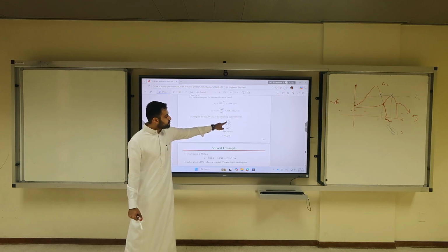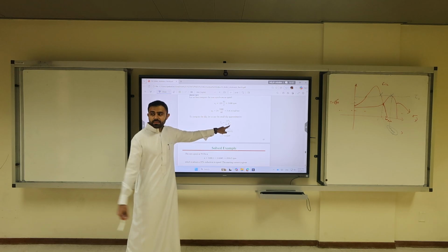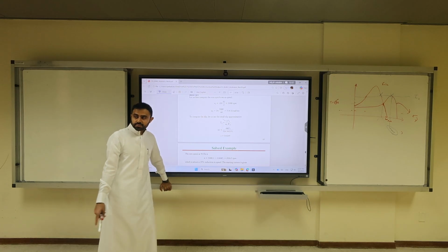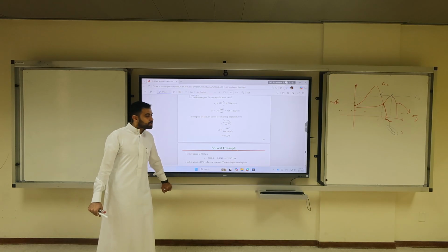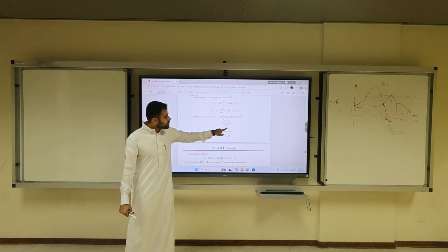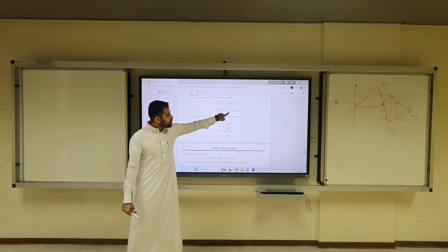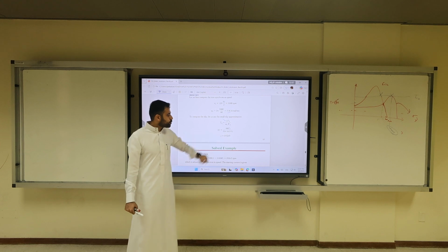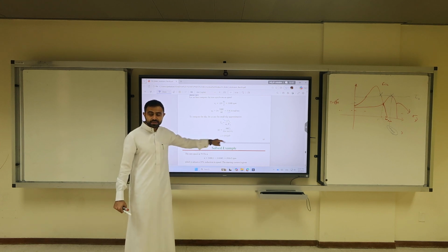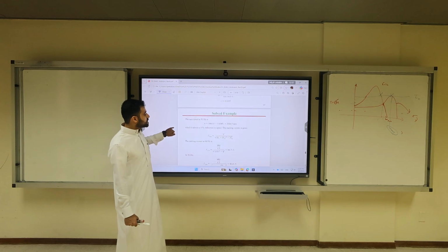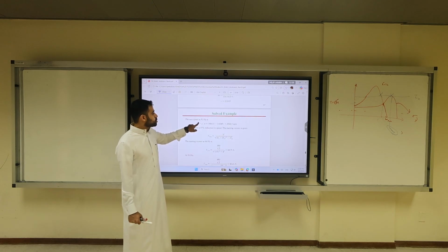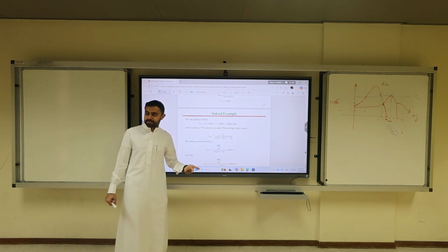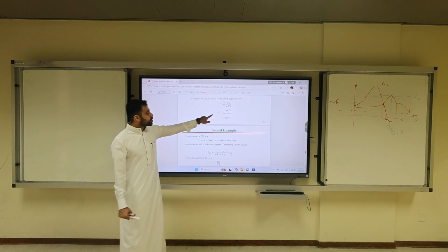This is the torque equation. T developed equals Vt squared S over omega S R2 prime. Is this line to line or phase? Line to line. So this V is correct. You have to pay attention, please, to the formula sheet. So this is 480 squared times S over omega S, which is 314, times R2 prime, which is 0.3, so the slip is 2.45%. Now, what is the speed at this level? It's 2926.